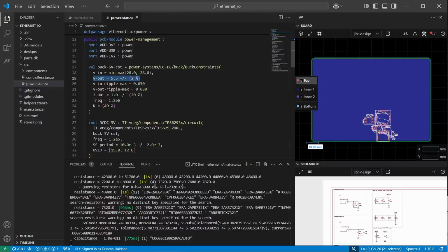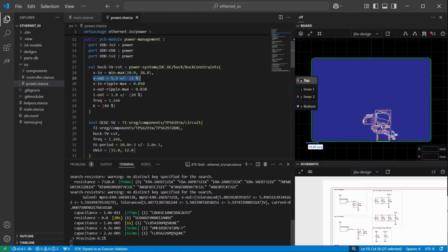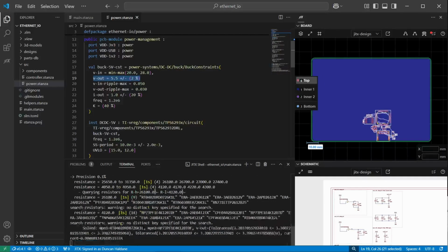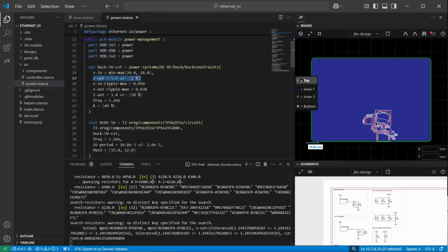And it's going to guarantee that under all variations of manufacturer tolerance and thermal variation with the TCR of the component, this output is going to be achieved, and making sure that those values are triply sourceable as well. And the nice part about that is that it's a solver you can write once and just reuse.